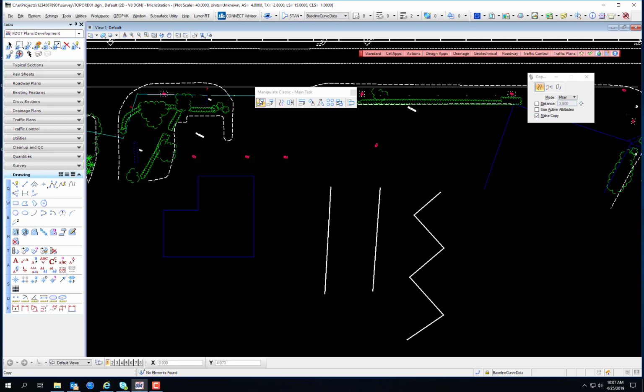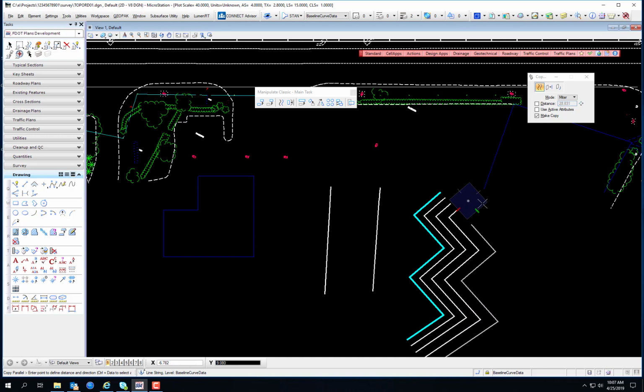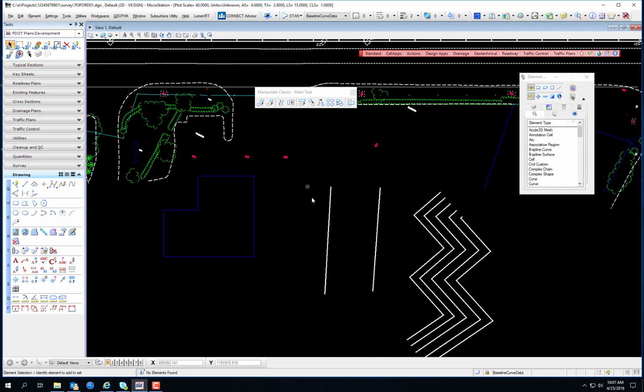So it used to be that the Copy and Move tools were the same tool. You just unchecked a box as to whether you can make a copy. The Copy Parallel and Move Parallel tool now still function that way. You notice it says Move Parallel, and then I check the box for copy. It says Copy Parallel. And so you can make concentric copies. It's absolutely excellent for making tile designs for floors. Okay. So that is the Copy Parallel and Move Parallel tools.